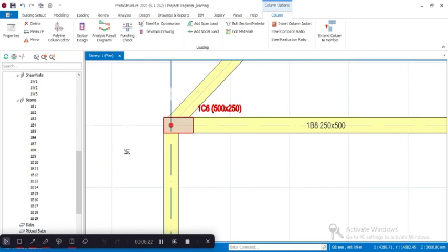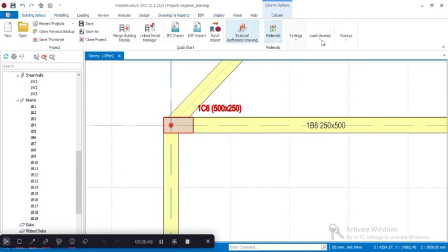Then select column. Okay, that's what we just did. That was JC1. I'll press the arrow key towards the right to move it inward. The step by which the member is moved can be set in building setouts, settings, view and save. So the member eccentricity step, you can edit the steps. Okay, let me show you that.